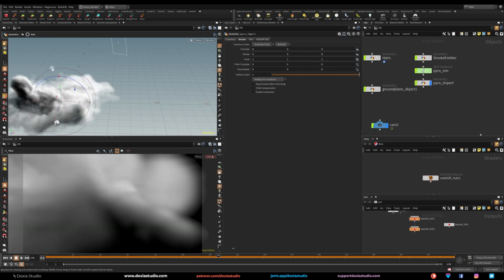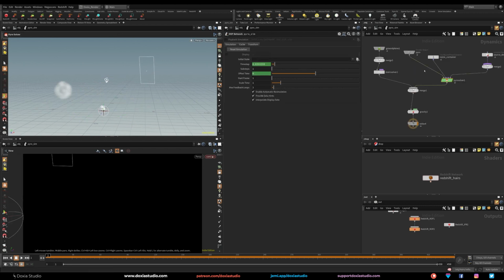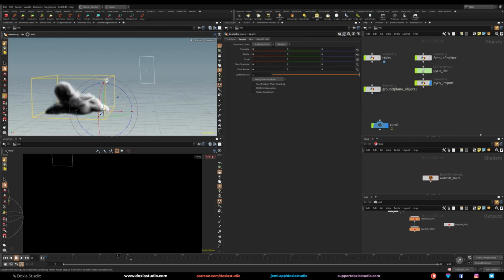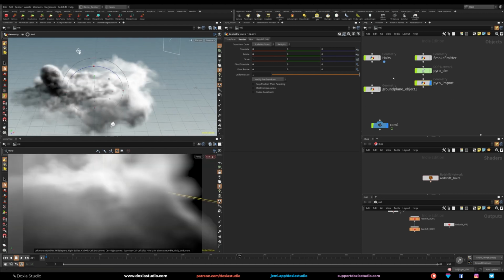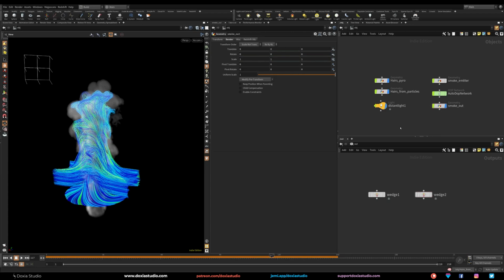So I have this pyro simulation. Okay, simple. On this one, let me go to frame 1. On this one, I didn't have any confinement. So this is processing. Let it think a little bit. On our pyro solver, on the buoyancy, I have 1 on X to go to the right and minus 1.5 to go to the floor. So that way I have this pyro simulation like this and colliding with the ground floor. Okay, so this is the only difference, but again, I'm applying the knowledge that we already covered in this tutorial.